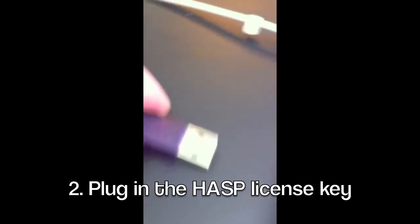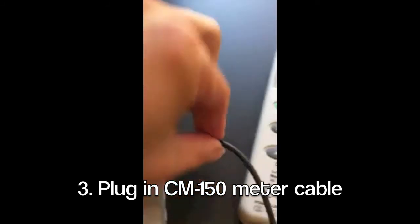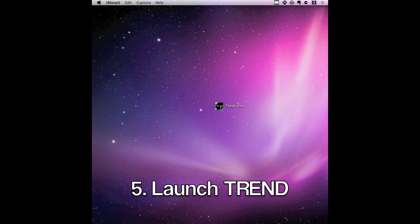Plug in the HASP USB license key. It will illuminate to indicate authentication. Plug in the meter's USB converter cable. Power on the meter. Launch the Trend application.